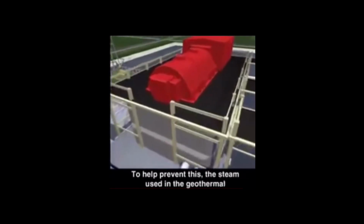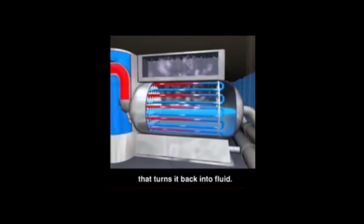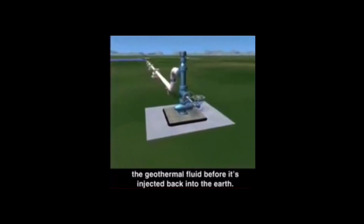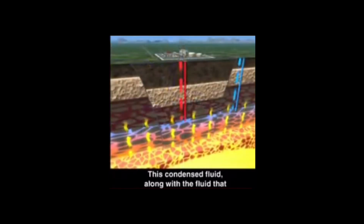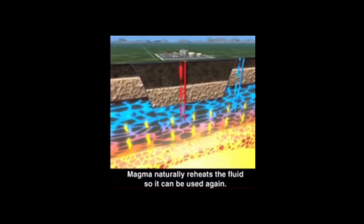To help prevent this, the steam used in the geothermal power plant passes through a condenser that turns it back into fluid. At this stage, it's possible to recover minerals from the geothermal fluid before it's injected back into the earth. This condensed fluid, along with the fluid that did not flash to steam, is injected back into the underground reservoir. Magma naturally reheats the fluid so it can be used again.